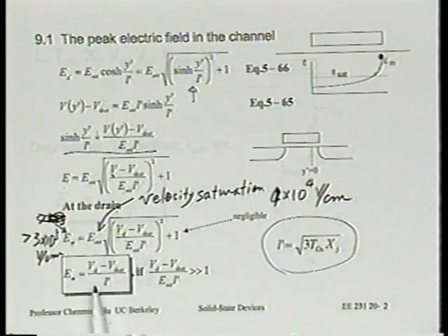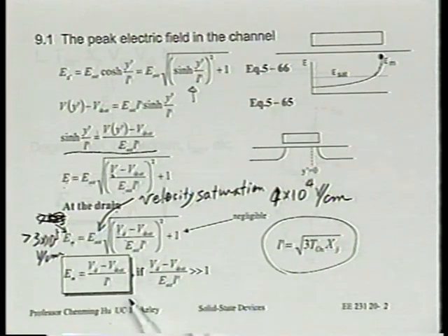It's well recognized that a scaled transistor simply won't work at high VD because of reliability, right? Hot carrier reliability, we can see now one reason why that's the case. When you scale the device, you have to reduce these voltages. And oxide breakdown is another problem, which is a subject of another chapter. Okay. Any question about this model of the peak electric field in the channel?